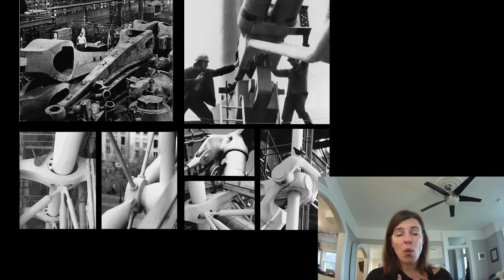I've gone through the process, so I know exactly how to do it, and that was my work with Cast Connex. But just to give you an understanding of what they actually do, they start with a positive mold. So you take foam or wood or something that's a very easy medium to work in, and you carve it into the shape you need it to be. Now we tend to work with CNC machines. Back then, they didn't have that sort of technology. And just to give you a sense of the scale of these Gerberettes, that's a person standing in amongst the Gerberettes.